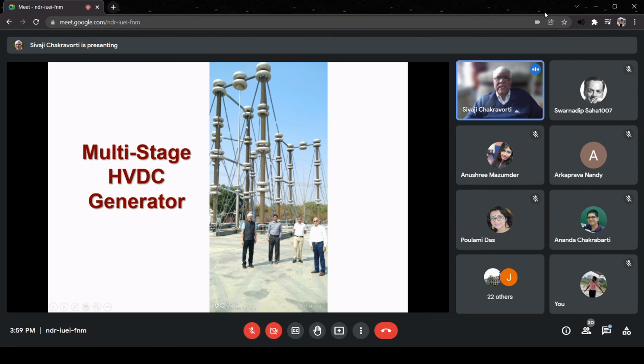And then in the end, we have always the potential divider. That's generally this vertical one, which, you can see here, there is no diagonal connection. So it's not a capacitor. This right one at the back side. Whereas these columns, they have diagonal connections. So they are actually capacitors vertically stacked.